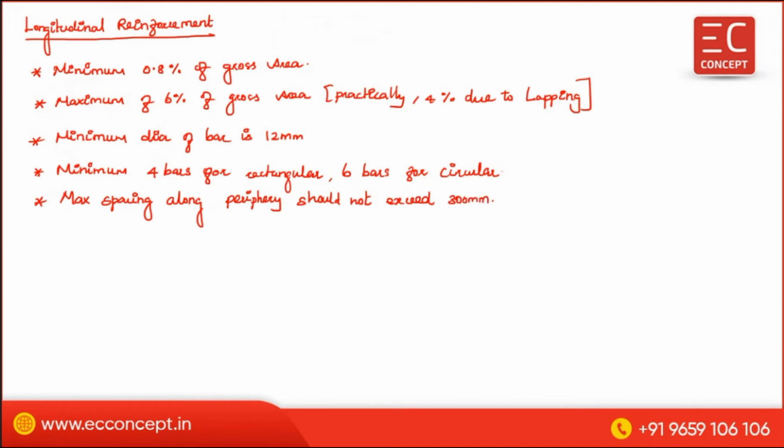Maximum spacing along the periphery of the column should not exceed 300 mm. Okay, so that is important.